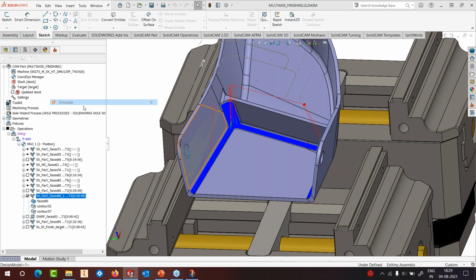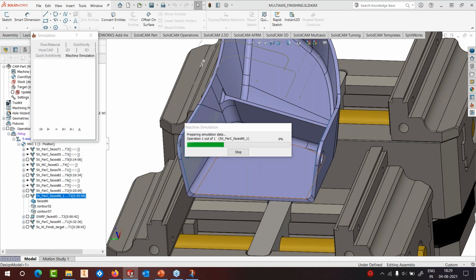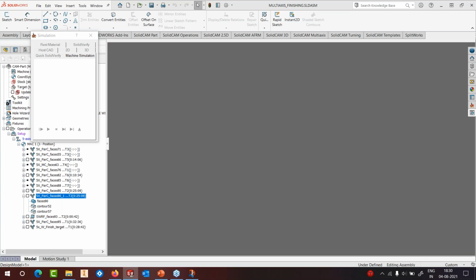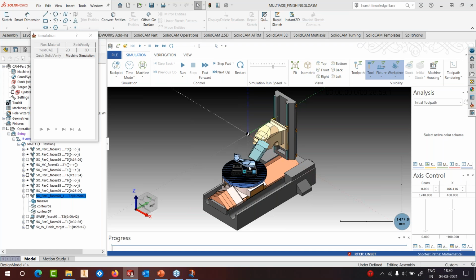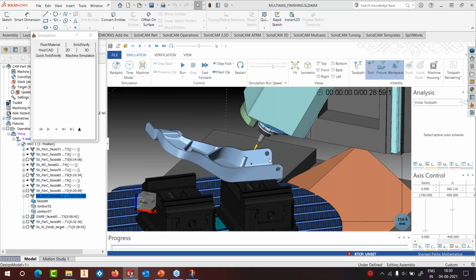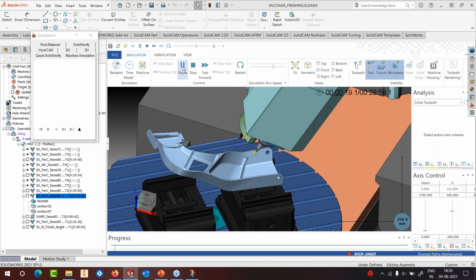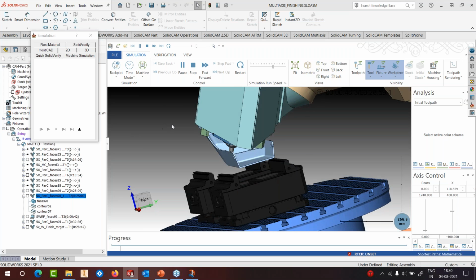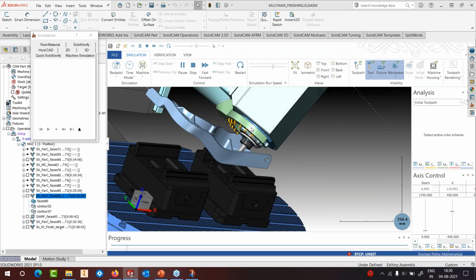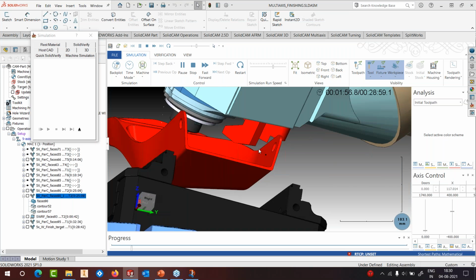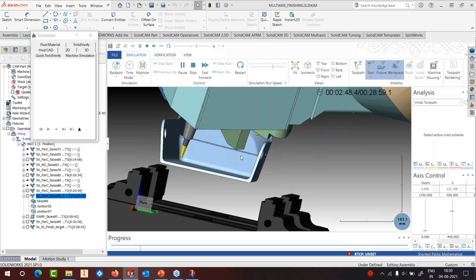Now, if I go into the simulation of the machine, that's how it's going to look like. Okay, so that's my tool material again. Let's run the simulation. So it's jumping between two. You can see that there are collisions because I have not provided any collision check to it. And one of the reasons why it is colliding is here. The element of the machine is colliding against the part. It's not the tool or any other geometry. The element of the machine itself is colliding.